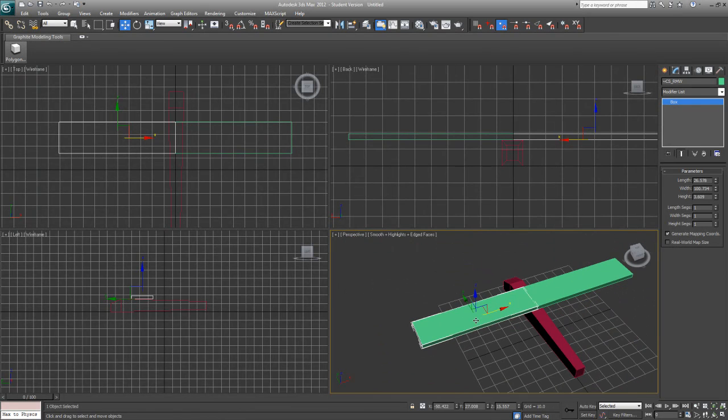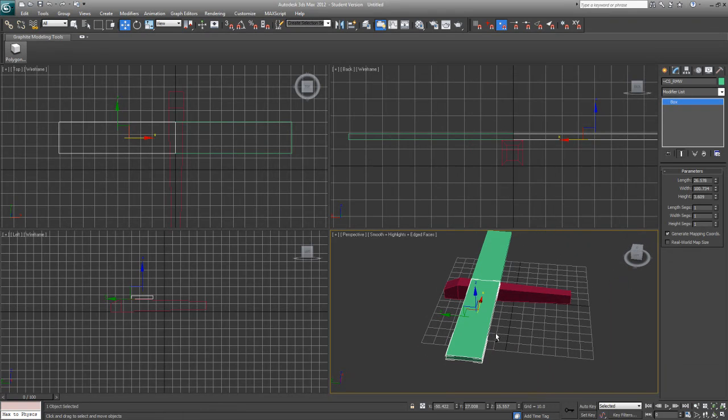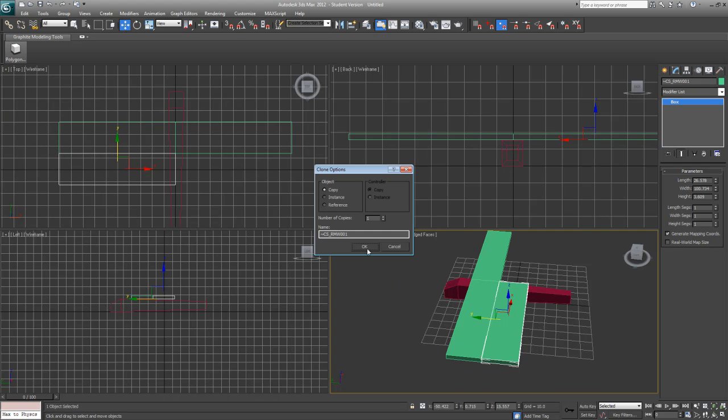Okay. So now a handy little thing we can do is we're going to need an aileron. So instead of making a new box, what we'll do is hold the shift on the keyboard, grab the Y handle, and just push back, and we got a gigantic aileron. Okay, and this gives us a chance to name it right here. We've made a copy. I'm going to take off these letters here, and we're going to call this, I believe I've misnamed things.